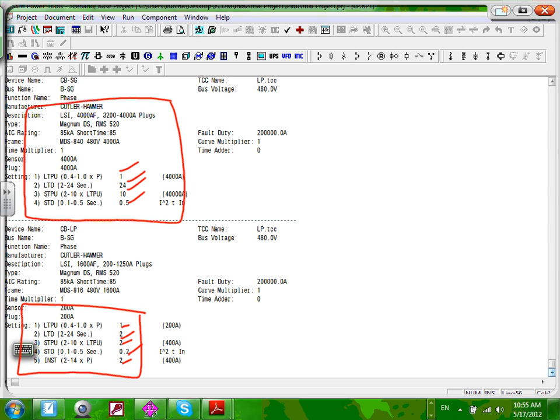This is one of the single most important reports that you're going to have. Cool? Don't worry if yours doesn't match exactly mine. And of course it has all the information about the plug and all this good stuff. Long time, everything. It also has the name of the circuit, the device name, the bus that it's connected to, how many phases, the voltage, fault current, tons of information about it. But these are the single most important things you're going to encounter.